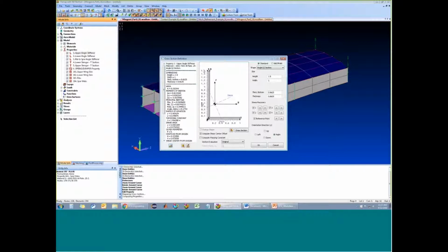We also have the rulers on here so we can see our size. And if I wasn't sure what some of these labels were, then I can click down here and there's a cross-section help diagram. And it tells me, oh, okay, this is the height, and thick bottom refers to this thickness versus just thickness refers to the side. If I want to go back and see my section, I just hit draw a section.